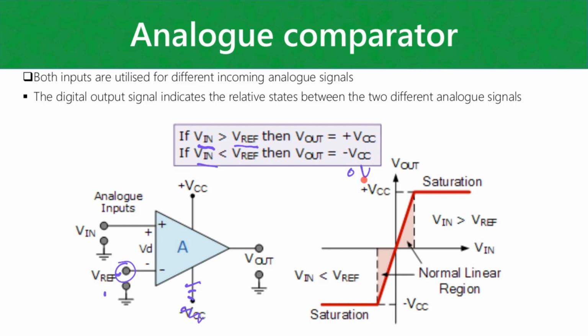If you don't really care about the analog nature of a signal, and you just want to know when that signal is above a certain threshold, and you want another circuit to operate during that time, or you need an output to switch on or off, then this circuit can help you with that. Very simple, but very effective as well. Something to keep in mind is that your amplifier is driven to saturation if you use it in this manner.